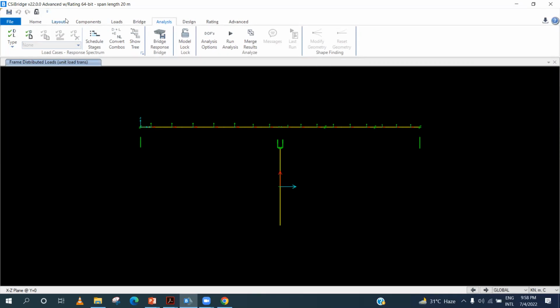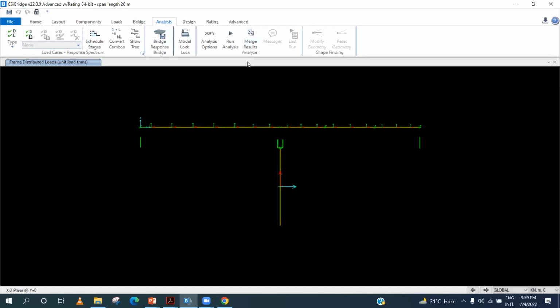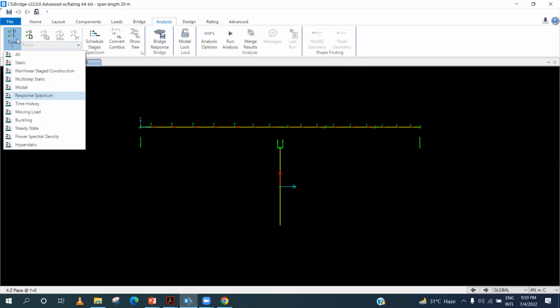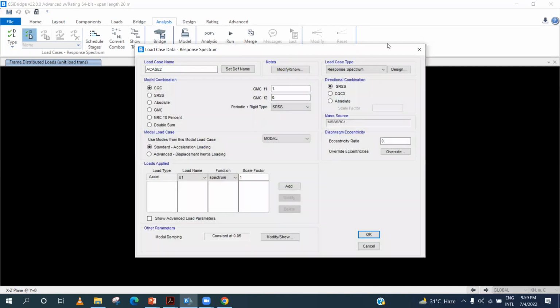One thing more, you might have used SAP or ETABS. In SAP or ETABS, there is this analysis model. Does anybody know what this does? What does this modal analysis do? I kind of remember it has to do with the participation of the masses. Yes, so basically I told you that multi-mode response spectrum analysis is where you discretize the structure. It is a very advanced topic, so you should have a very good understanding of dynamics of structures and seismology to perform such analysis.